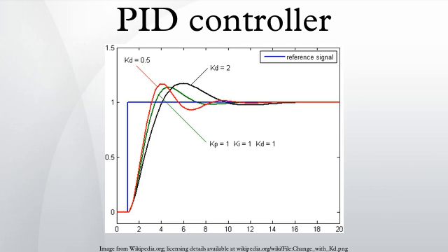Bumpless operation. PID controllers are often implemented with a bumpless initialization feature that recalculates an appropriate integral accumulator term to maintain a consistent process output through parameter changes.